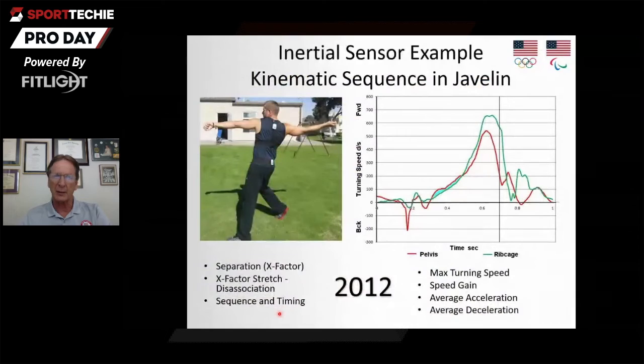Because we were outside, we didn't use the motion analysis systems anymore, since optical-based motion analysis systems definitely don't work very well outside. And one of the disadvantages of the electromagnetic system that I forgot to mention was that it's wired and tethered. So it didn't really work with sports that involve moving, such as running or jumping. It did work with golf and baseball because there's not as much motion and they stay pretty much in one spot. So anyway, we got on to using inertial sensors, and here's an example.